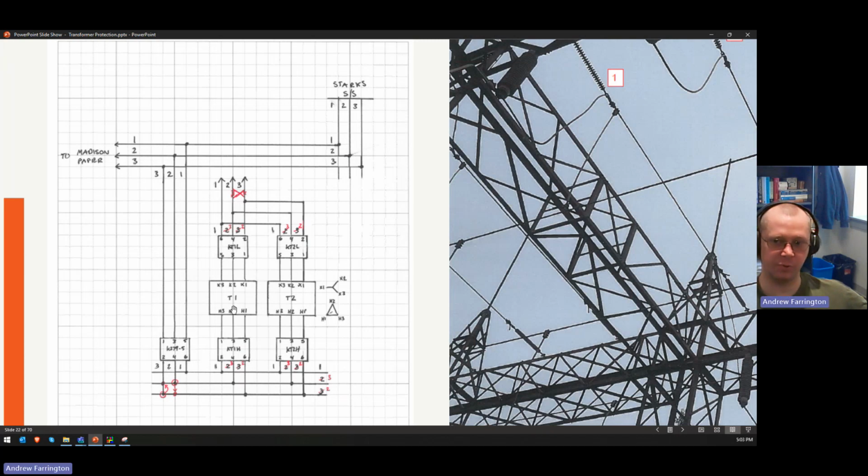And then we traced it through to the H1, H2, and H3 bushings of the transformers and found that, yes, in fact, there were two swapped phases, and they were all DY1 transformers. So the 34 kV was 60 degrees out of phase, and thus the reason they couldn't use that switch. So we added that to the list of things to fix during this outage.